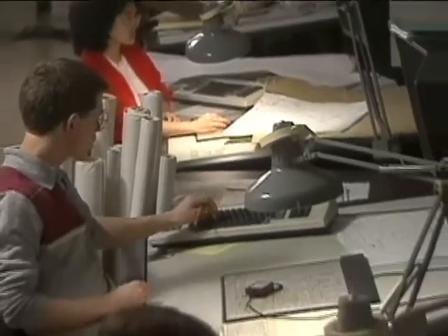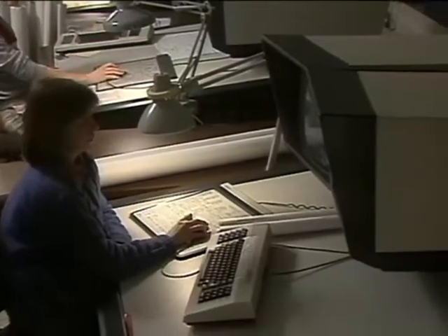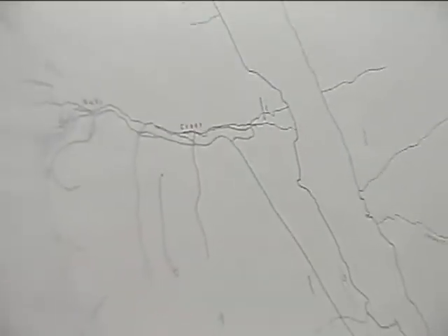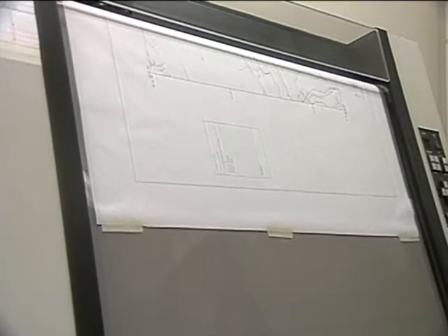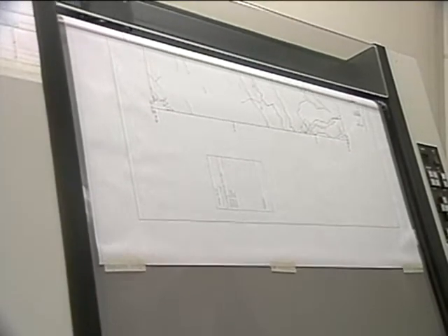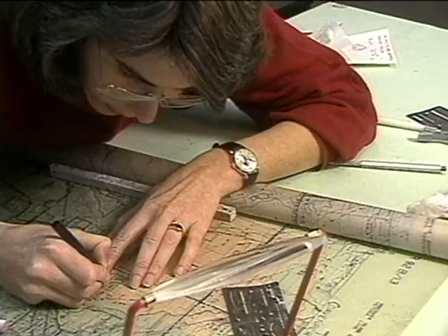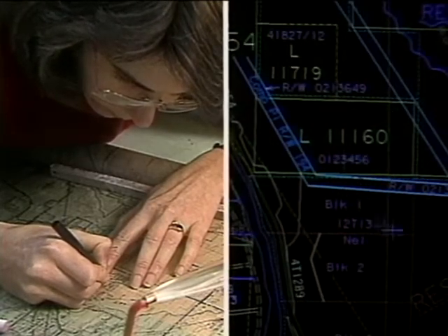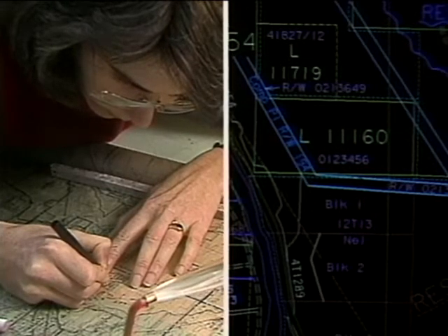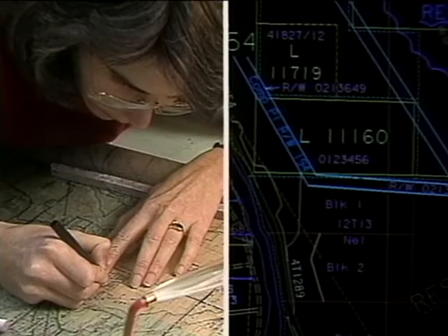The field offices supply relevant background information to the Surveys and Lands branch, where it is incorporated into the reference maps. As encumbrance information is updated, the maps are easily revised in both the automated and hard copy formats. The most important feature of the graphic system is that the automated format for cadastral reference maps can be updated and corrected instantly to reflect the most current information.